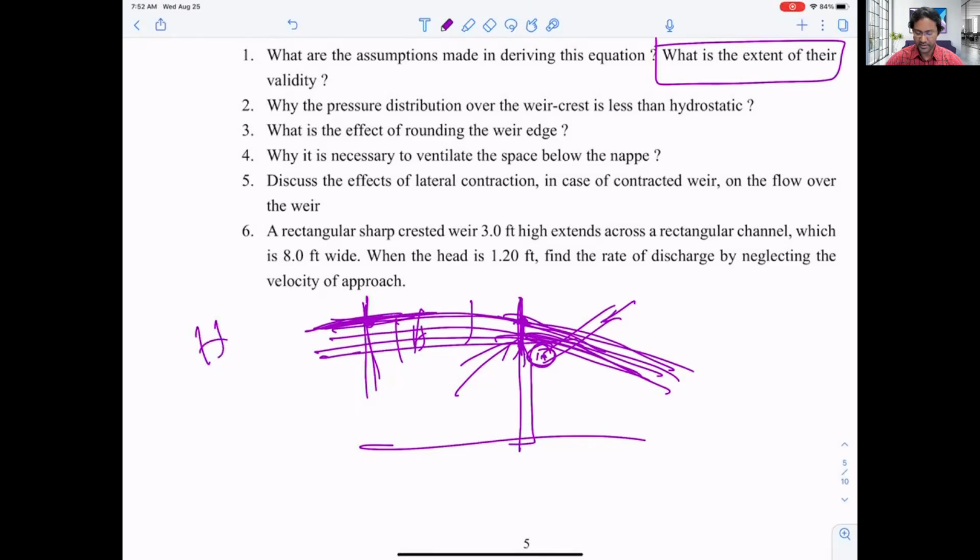So that's why we need to ventilate. Otherwise, if we don't ventilate, water will be everywhere, and it will be kind of submerged, and we'll have pressure from downstream, and this won't be like the head we had in the ventilated condition. The head will be reduced, then the flow rate will be decreased. That is not our main point.